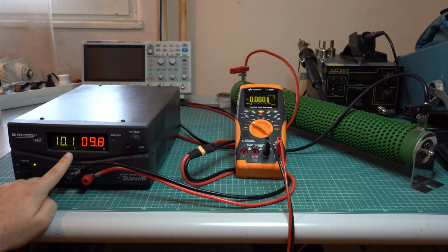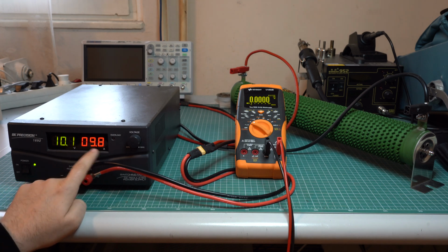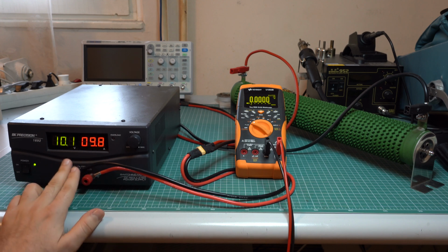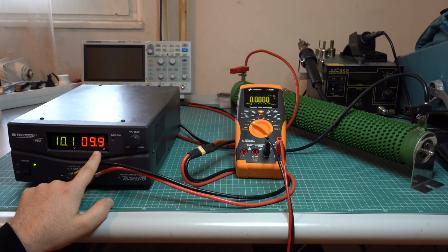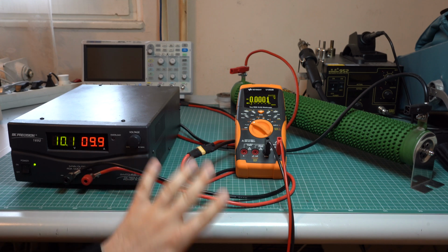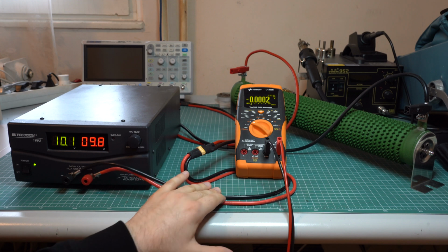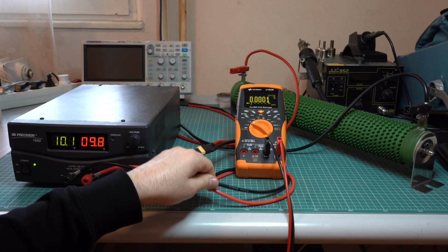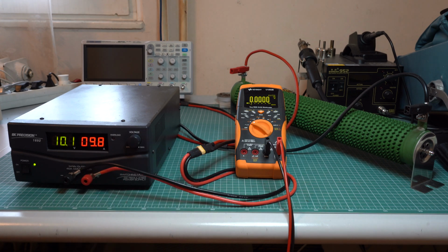So as you can see, at 10 volts we have a current of about 10 amps, which is exactly what we expected. However, we also have some differences here, so we can see that the current is slightly lower. And if you're wondering where this difference comes from, well, it's mainly caused by the resistance of these wires. So ideal wires would have 0 ohms, however there is no such thing as ideal wires. So you have a certain voltage drop on these wires which impacts the measurements just a bit.